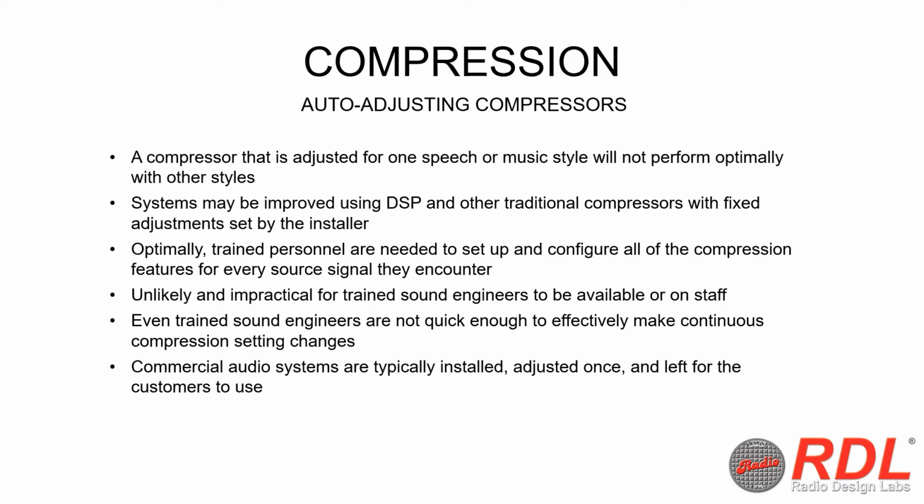Here's the challenge. Audio signals come from a large variety of sources and styles, including live presenters, video and audio conferencing, paging, audio and video playback content, stream music, and much more. A compressor that's adjusted for one speech or one music style will not perform well with other styles. Basically, every source and style needs to have individually configured compression.